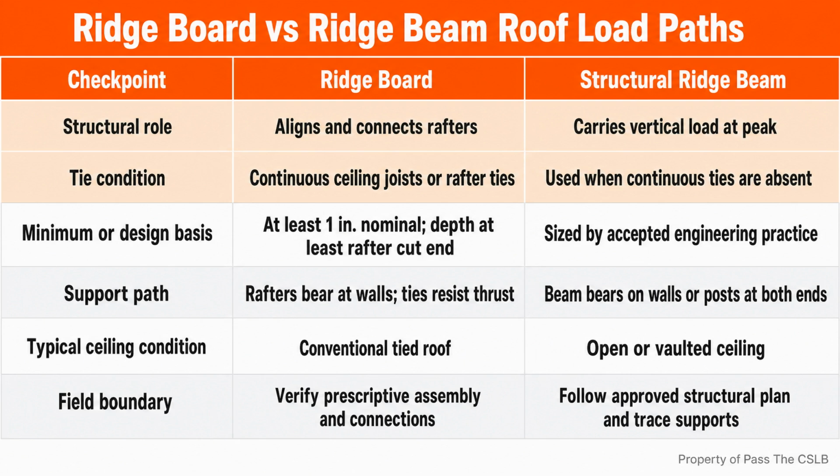Imagine a contractor who is opening a flat ceiling to create a vaulted room. The crew removes drywall, sees ordinary ceiling joists, and starts cutting them because the owner wants a clean open space. Suppose those joists are the members tying the rafter heels together. As the ties disappear, the rafters can begin pushing the exterior walls outward.